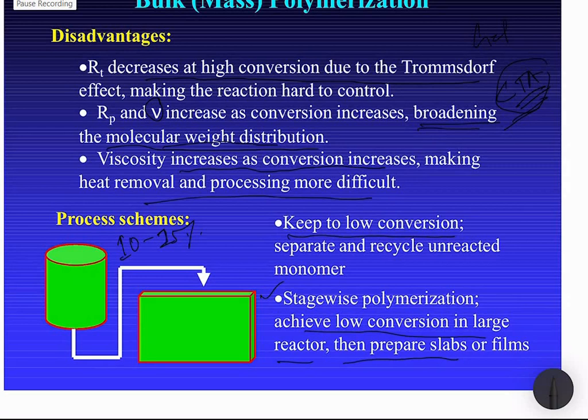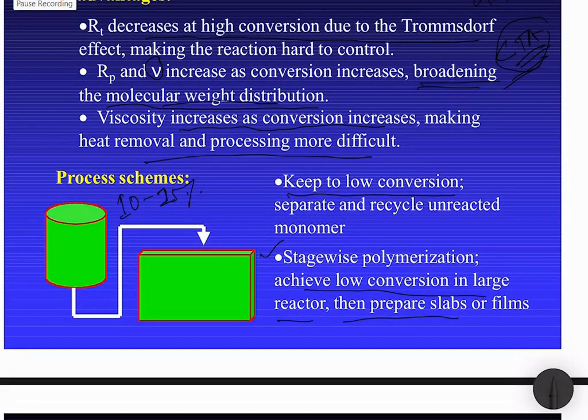And also that way, if some gel formations, local cross linking, local charring, these sort of things happen, that actually makes the polymer processing more difficult and more energy consuming. Now, because of these disadvantages, the polymerization in bulk mode is being carried out in stage-wise mode, whereby initial 10 to 25% conversion of the monomer is carried out in a big tank through stirring.